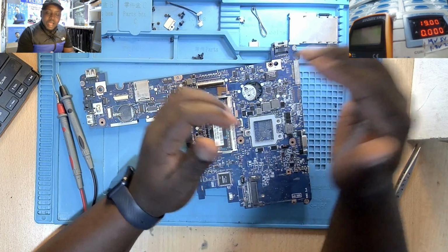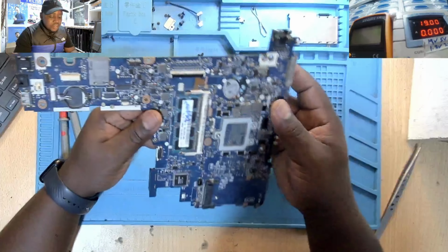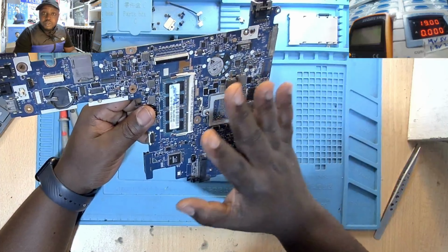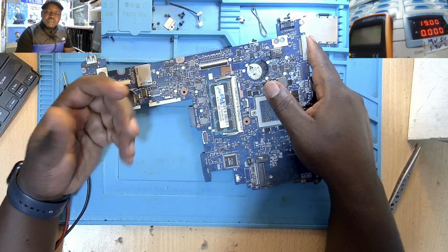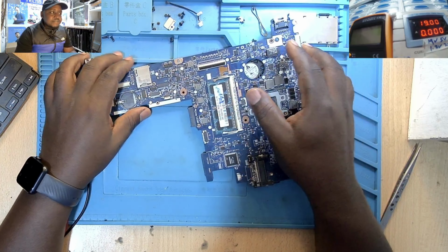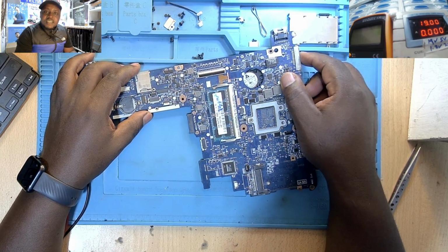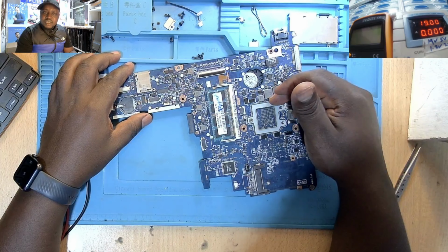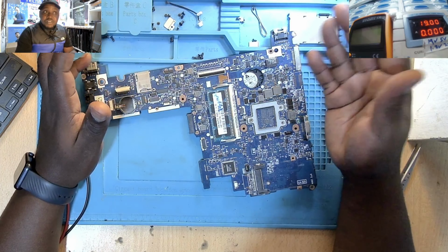So after that, I'm just talking about the faults you can find through tools. Now I want to talk about the faults you can check with your bare eyes, just visually, and be able to see what's wrong. We have very normal things in visual inspection and diagnostics, like water damage, or a burnt component because of a short or overheating. Those things you don't need a motherboard or a power supply to see. You just use your eyes.